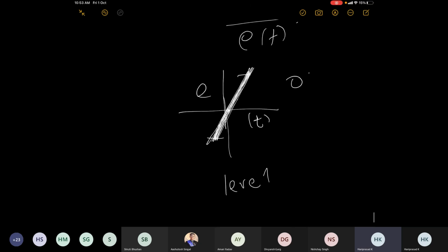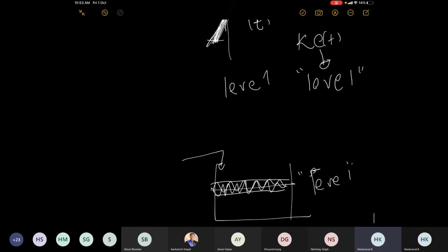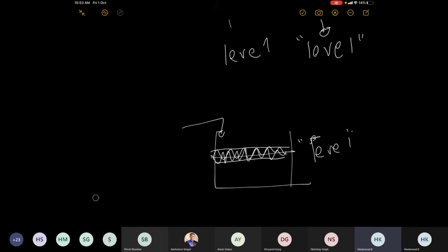So your controller output is also varying. When you use proportional control for level, it is okay. But for many variables like composition and temperature, you cannot tolerate any level of oscillation. Flow is okay because inherently when you fill in the tank, it would tend to oscillate.